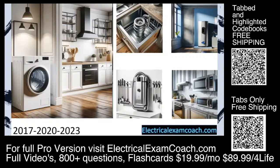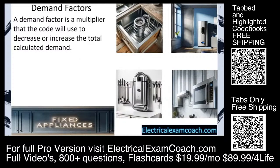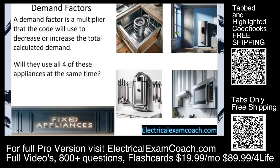Let's get to it. Before we dive into the calculations, let's learn about demand factors. We're going to be using them for the rest of the program. A demand factor is a multiplier that the code will use to decrease or increase the total calculated demand. The question is, will they use all 4 of these appliances at the same time? And the answer is no. So the code makers have made it so we can reduce the overall demand. Instead of just counting them watt for watt, they've made some multipliers that allow us to reduce the demand that we calculate. And remember, if we have fewer amps, we could have a smaller service. If we have a smaller service, we could have smaller pipe, smaller wire, and a smaller overall cost of the job.